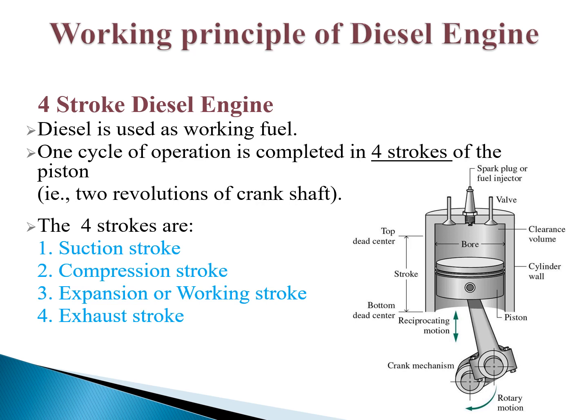In the case of the four-stroke diesel engine, we have to understand that there will be four strokes in this engine. That means the piston moves from top dead center to bottom dead center, that is the first stroke. Then bottom dead center to top dead center, that is the second stroke. Then from top dead center to bottom dead center, that is the third stroke. And after that, from bottom dead center to top dead center, that is the fourth stroke. The movement of the piston is marked as the stroke, and these four strokes are given four names, as given in the slide.